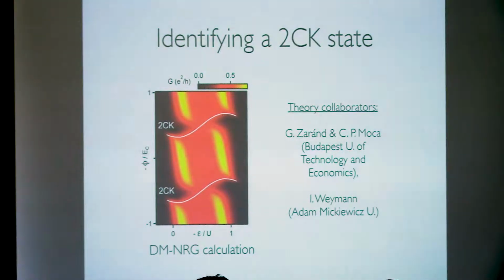measured in equilibrium as a function of, on the left axis here, the gate voltage for the metallic grain or the big dot. I'll use those terms interchangeably. And the gate voltage for the small dot. So right in the center here, if I were to make a vertical cut, that's when I have one electron on the small dot, and then I can deplete it or add another electron by going to either side of this plot.